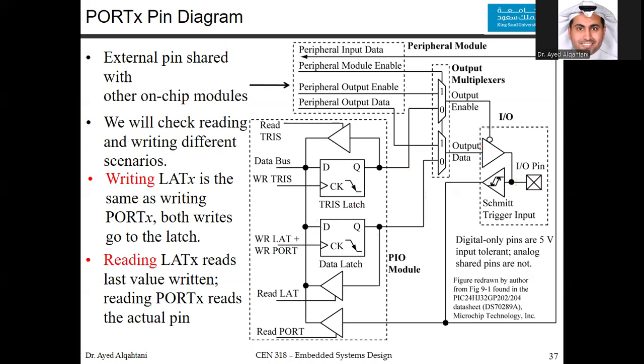I didn't want to jump and say it at the beginning, but writing LATx is the same as writing PORTx. Both writes go to the latch, but reading is different. Reading LATx reads the latest value written. Reading PORTx reads the actual pin directly. And that's the main difference.